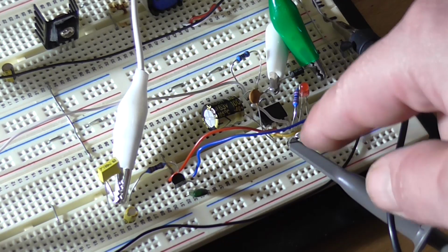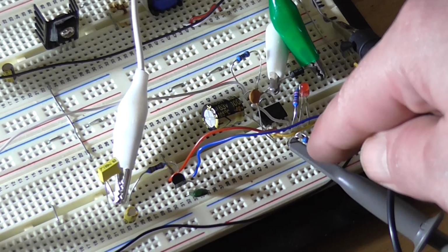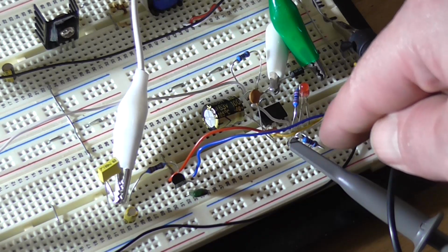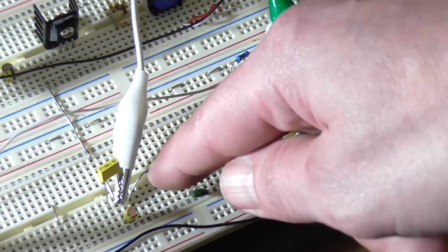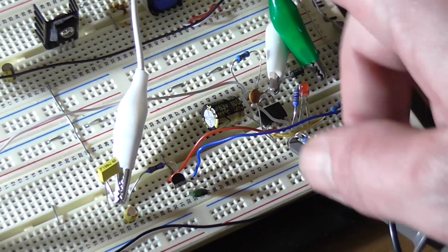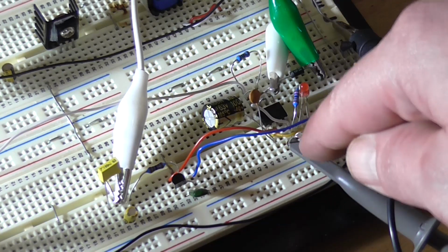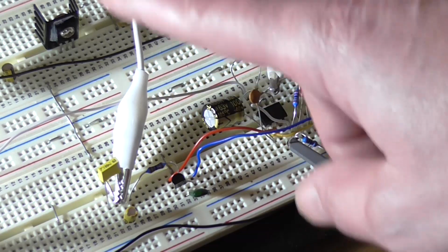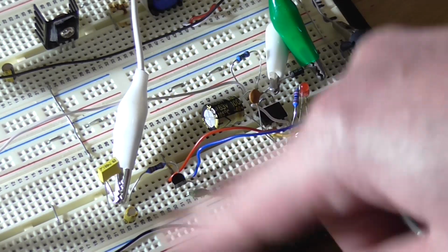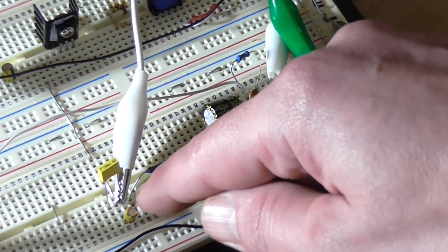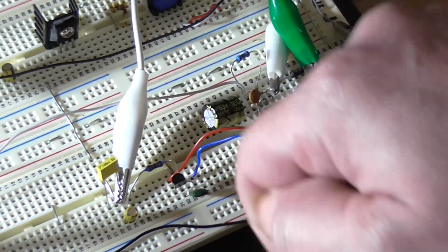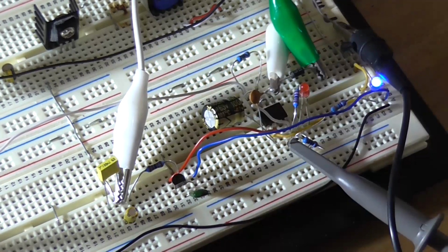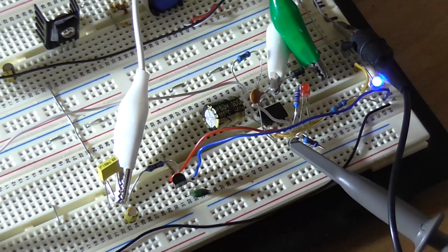So either this 1K resistor is too low and needs to be increased, or it's maybe an impedance issue here at the input. I don't think it's an impedance issue. I think it's more like this resistor is too low of a value. What I will do, though, just out of curiosity, is add a resistor from this side of the capacitor, the transistor side, to ground, say 10K, just to give it some form of input impedance here across this capacitor, and see if that makes a difference. I don't think it will.